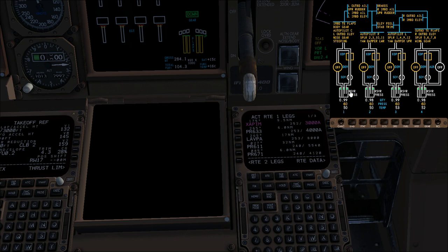As you know, the reservoir for the hydraulic system is pressurized at a few psi, around 50 to 100, usually lower, around 50, to improve the positive flow from the reservoir to the pump, because the hydraulic pumps must have a positive fluid supply to prevent cavitation, and so pressurizing the reservoir itself improves the positive flow from the reservoir to the pump.